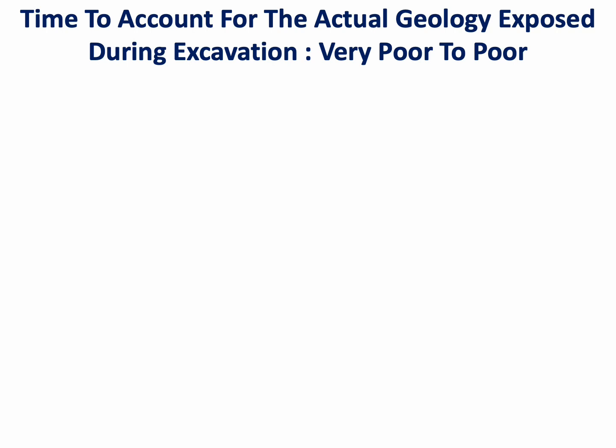Now that was the time to account for the actual geology exposed during excavation. When in 2012 those shear zones were met in the construction area and in the main access tunnel to the powerhouse, and later on it was confirmed that in the central gullet of the caverns the same shear zone is intersecting the three caverns throughout their depth. That was the time to account for the actual geology exposed during excavation in the layout design and design of rock supports.